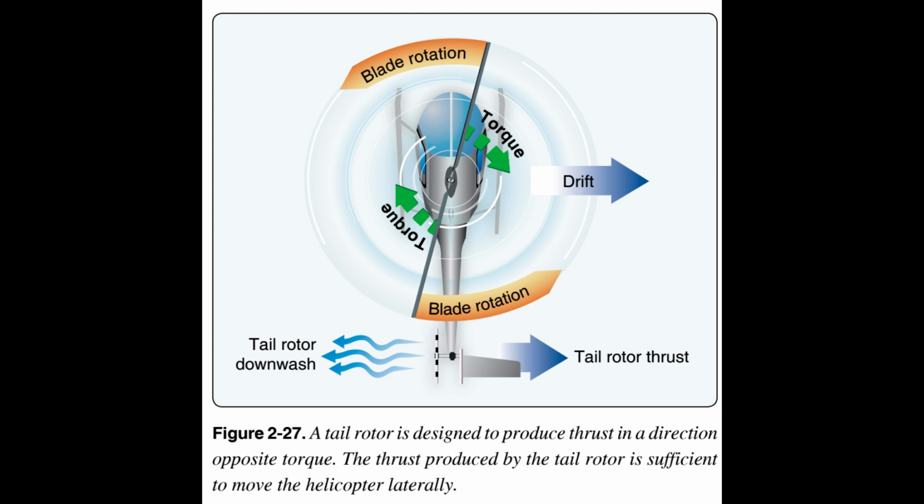In forward flight, the tail rotor continues to push to the right, and the helicopter makes a small angle with the wind when the rotors are level and the slip ball is in the middle. See page 12-2. This is called inherent side slip. For some larger helicopters, the vertical fin or stabilizer is often designed with the tail rotor mounted on them to correct this side slip and to eliminate some of the tilting at a hover.